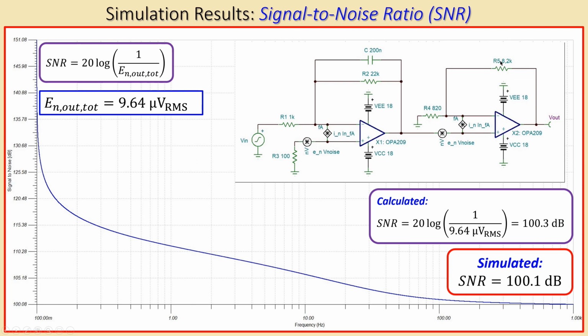So you can make this 10 times smaller and also this 10 times smaller. You still have the gain which you require, but your resistors are smaller, but it will of course also result in more current, also more power consumption. So there is some optimum between noise and power. You can also do the same thing here and also here. So that really depends on what you require for your application.